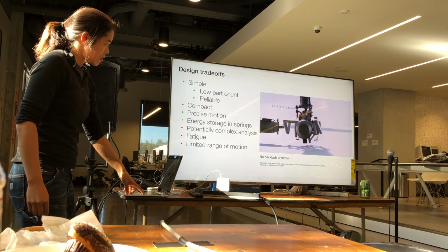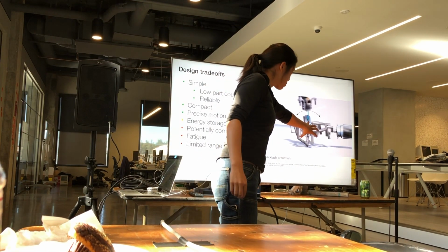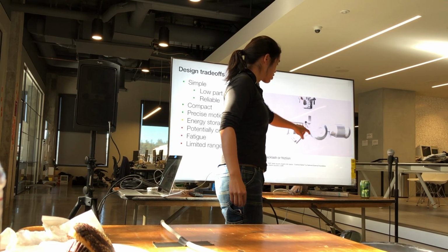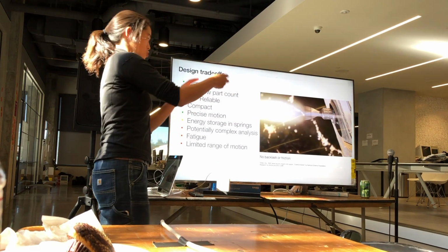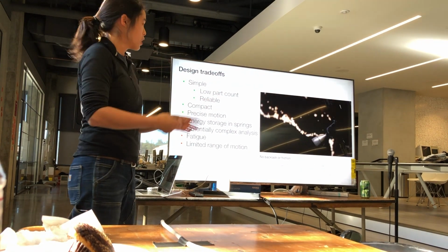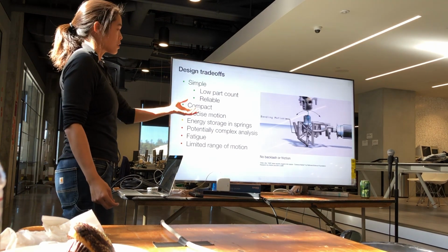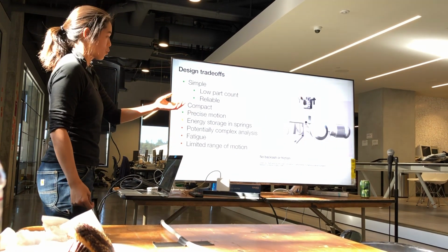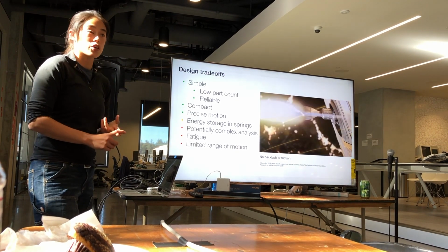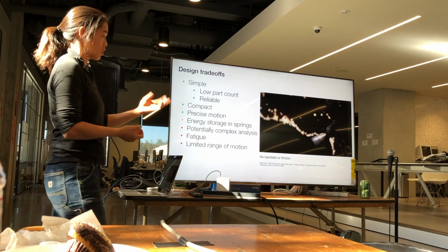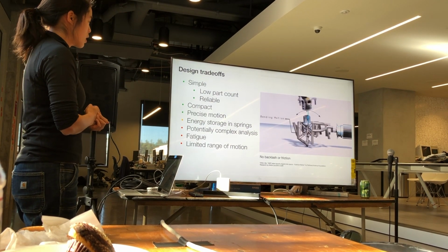Here's that thruster thing that I talked about. In the middle, you have a 3D printed titanium compliant structure. There are two input motors which give you 2-axis control of this thruster. I think this is a really awesome demonstration of a lot of the benefits of compliant structures. If you did it with traditional mechanisms, you would need gears, bearings. It could end up being quite heavy. It could end up being larger. Both of those are obviously constraints for launching satellites.